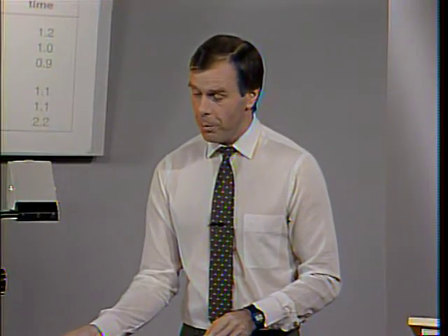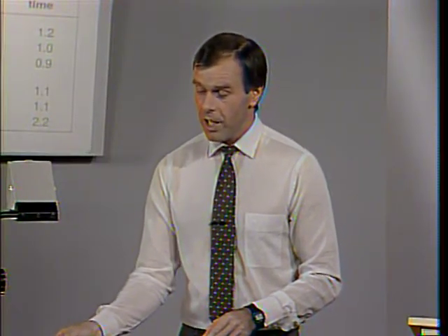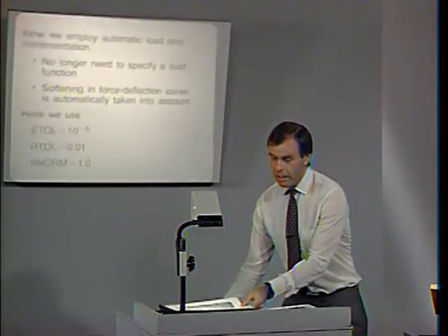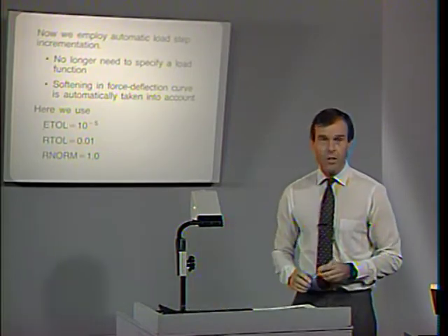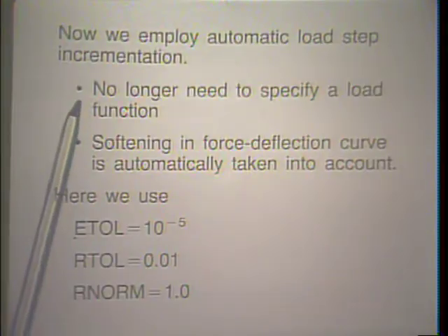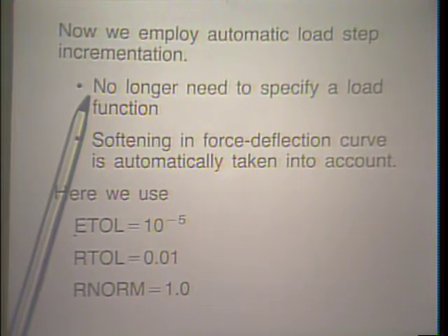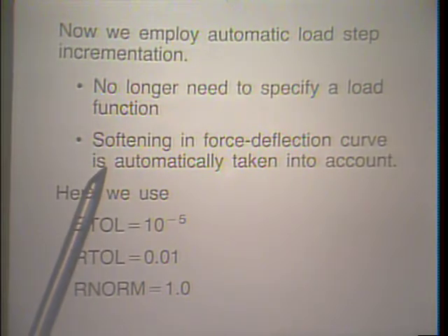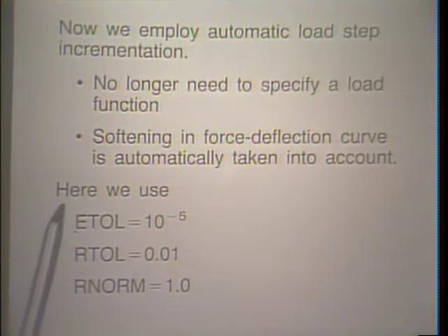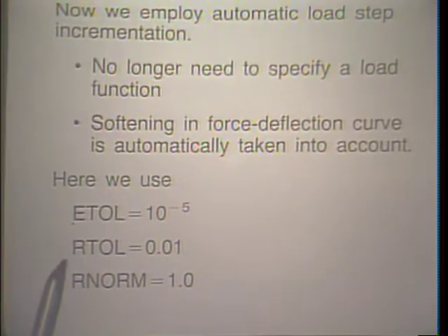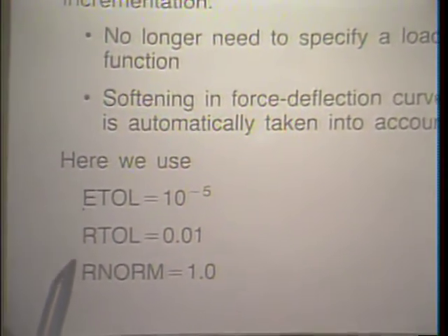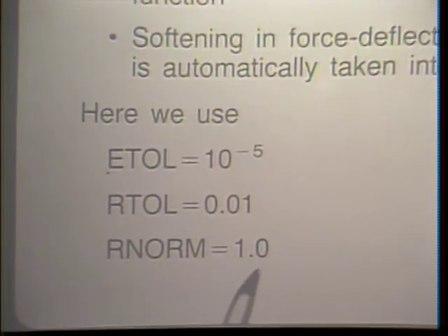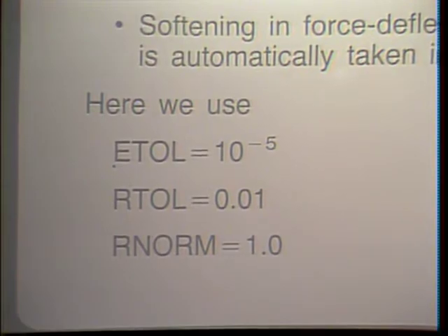Once again, please refer back to the previous lecture in which I have been discussing these various solution techniques. If we use the automatic load step incrementation, we do not need to specify a load function anymore. We discussed that earlier. And the softening in the force deflection curve is automatically taken into account. With this technique, these are the tolerances that we used. Default tolerances in Adina here, and this is the same R norm value that we used in the earlier analysis.